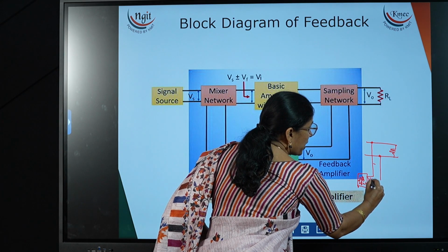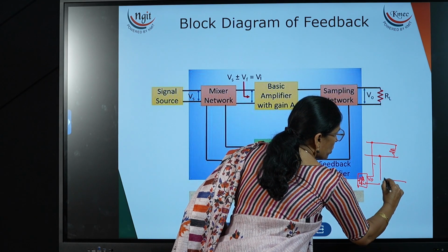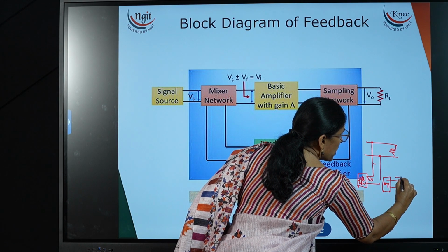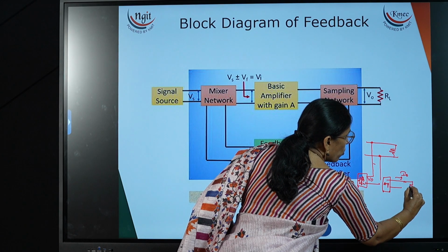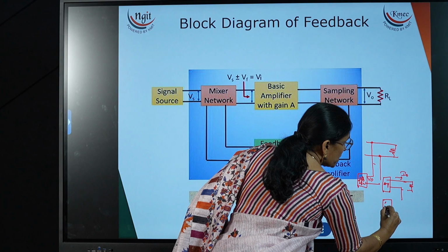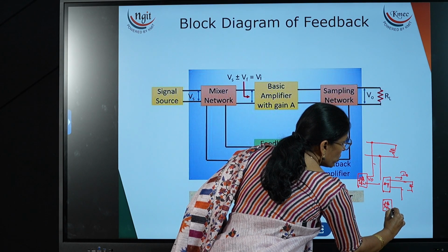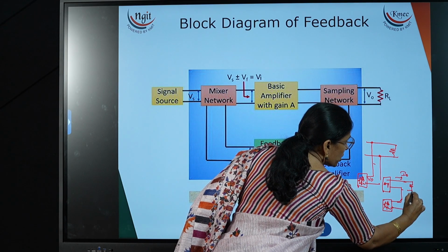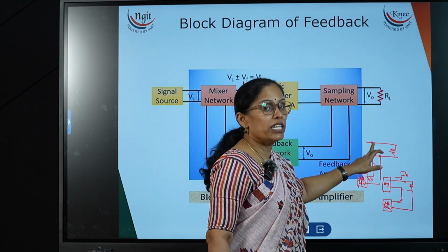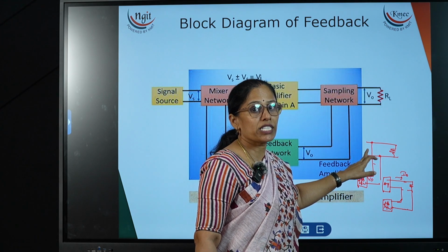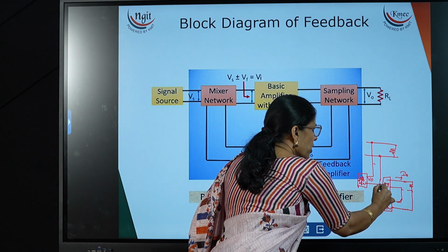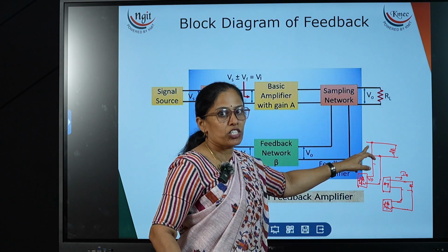If we are taking current, then this is an amplifier circuit, and from the amplifier the current I0 is coming to the load. Now the same current we have to apply to the feedback network. Here we are making a series connection. The voltage sample is taken in a shunt or node, since voltages are the same. That's why to take the voltage as a sample, we give the node connection or shunt connection.